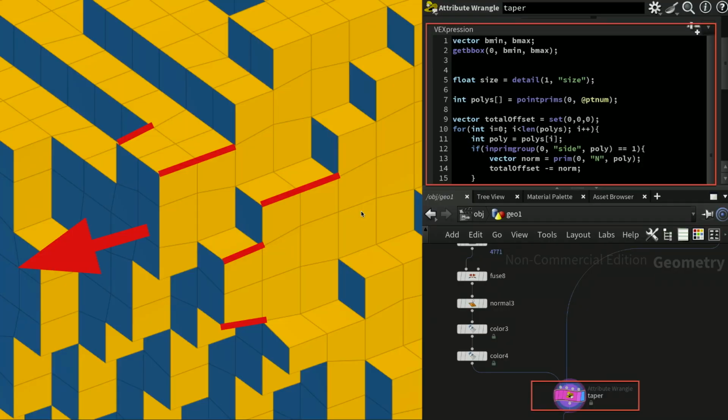And once we have this voxel shape, what we need to do next is to make sure there are no hard frictions on the mold directions. So we needed to assign some tapers to each of the planes, which is on the top and the side, perpendicular to the mold directions. These tapers reduce the frictions, making it easier to remove the final ceramic objects from the mold.